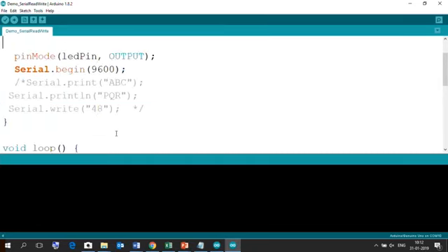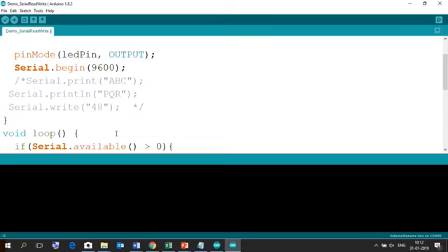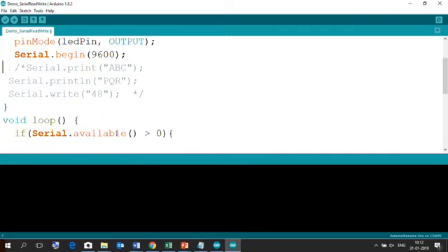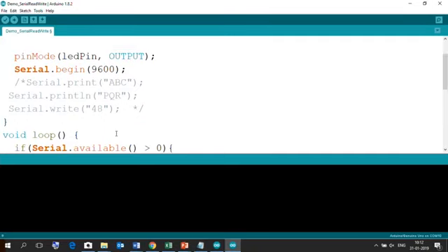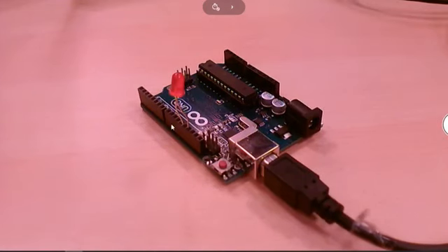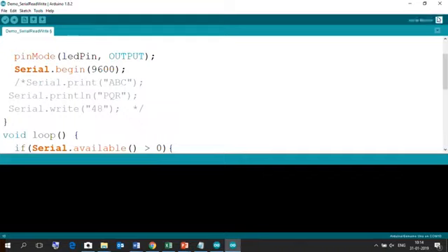So, simple. We want to see that serial communication. Take the input coming from some serial pin, but just for a sampling here, we will take the input from the serial monitor that is available in this IDE and actuate the LED. To put this particular LED on, I have to send some serial input. So, let us come back to the IDE here, go to the serial monitor. This particular input field is here to take the serial input. I enter 1 and press enter here.